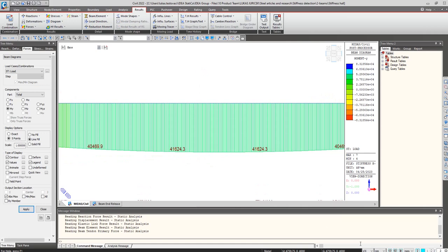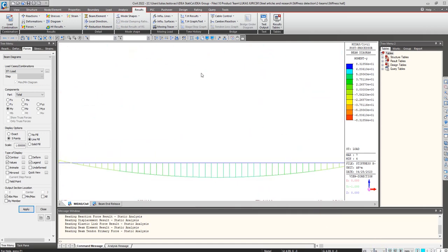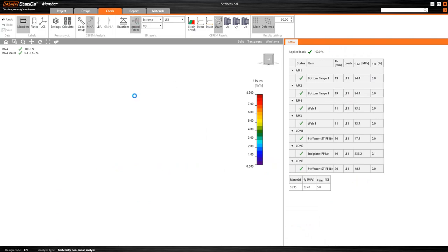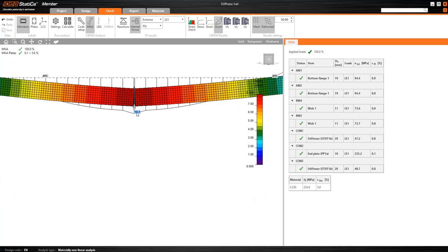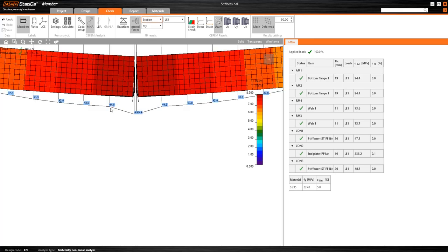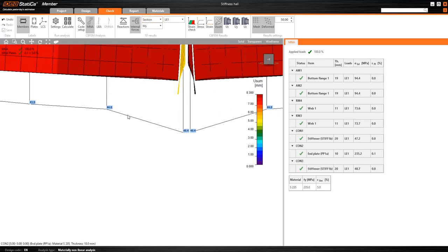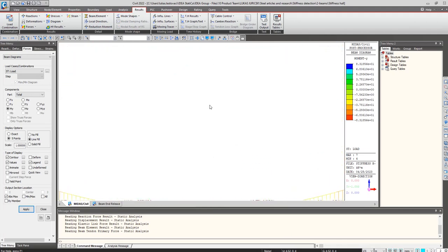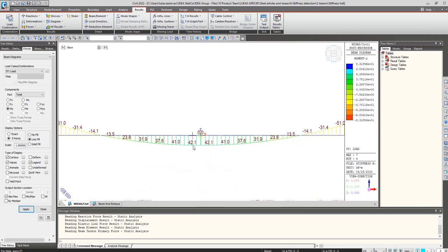In the middle we can see approximately 42 kilonewton meter, and the member is showing some drop close to the area of the joint. So if I don't want to see only the extreme but the section close to the area of the connection, you can see I'm about 45. So this is also a very good correlation with the bending moments for linear stiffness here, and for the nonlinear we can see approximately 42 kilonewton meter.